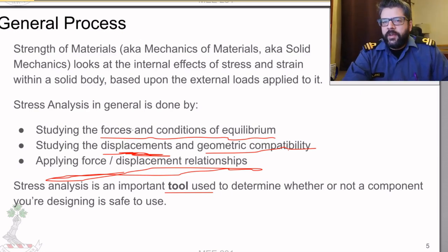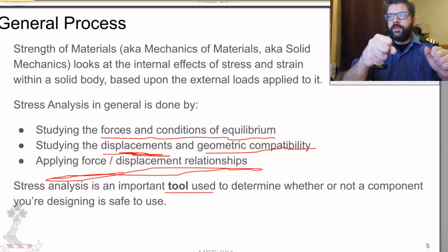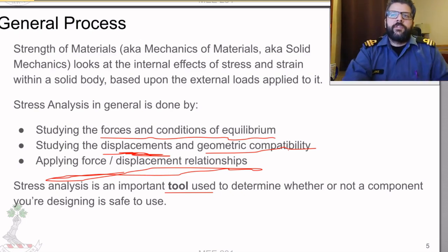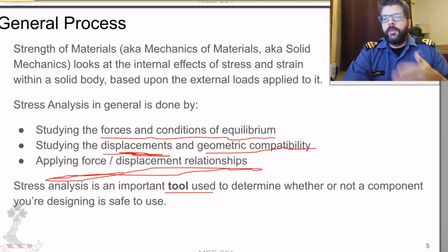And usually what we want is we don't want it to be yielding at all. So we don't want any permanent deformation going on. Basically what that means is that if we load it up, if we pull on something, it's going to stretch a little bit. But when we relax, it returns back to its initial shape. So there's been no permanent deformation, so it stays elastic.